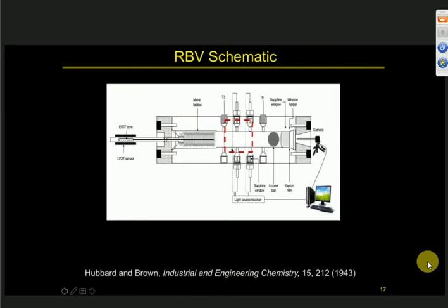In this schematic, as I showed, there are four small window holders. You shine light from one window and detect the light on the other side. We use the light to detect the ball motion. You have the cell, exactly like what I showed you for measuring the density and phase behavior, but this is a little bit longer. Then you have a ball here, and a borescope and the sapphire window to look inside the cell. The back end is a bellows connected with an LVDT rod.